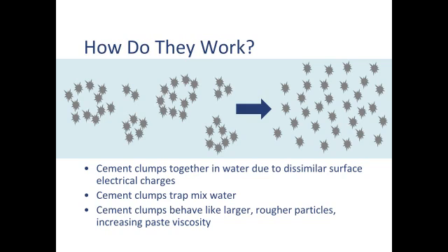So you've lost some of your mixed water or trapped it, and these particles are now big and rough and angular, and they don't move around each other. And that's why that mix seemed so dry. That's why that mix was so difficult to work with. You would be so tempted to add water to it. But obviously, just by adding some powder, there was more than enough water in there. And this is sort of the insight.